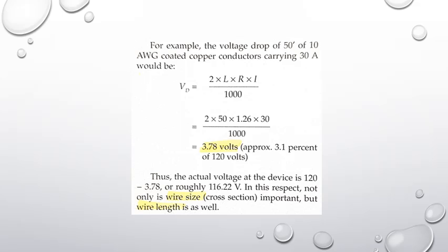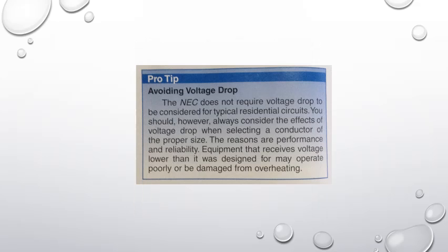Ampacity is the maximum current carrying capacity of a wire and its consequent heat dissipation ability. Table 310.15(B)(16) lists the ampacity ratings of each standard wire. See figure 5-8. You can select a wire size from the table